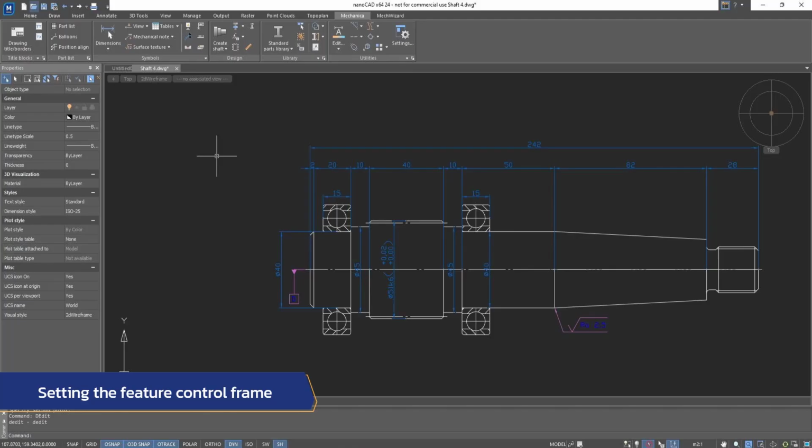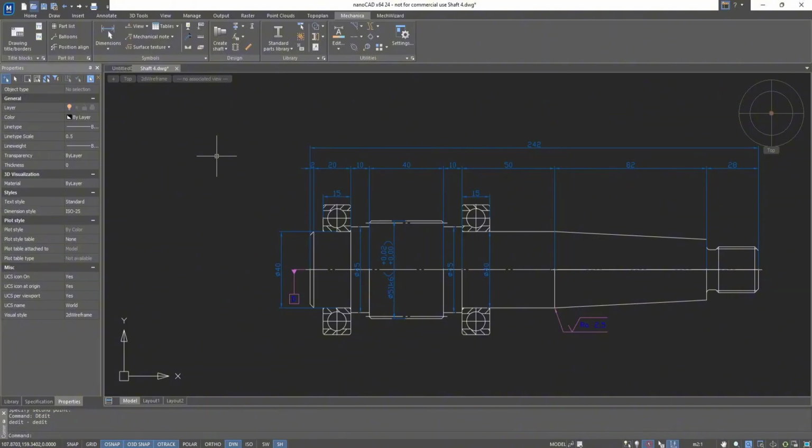After placing the base, we can assign form tolerances to our part. Why are they needed? In modern manufacturing, every part is made with a certain accuracy. To define the permitted manufacturing error, form tolerances are introduced. These parameters are indicated on the drawing using a tolerance field and a base, as dimensional deviations must be calculated from a base point or surface.